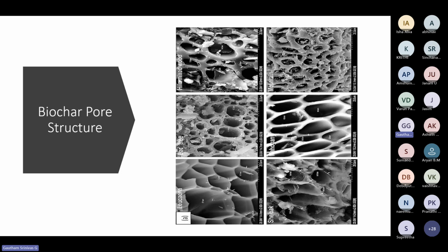It can also be used as an adsorbent in many applications. For example, if you have a mixture of gases that has carbon dioxide and you want to separate the carbon dioxide, you pressurize the gas to more than 12 or 13 bars, and the char has high affinity to carbon dioxide.